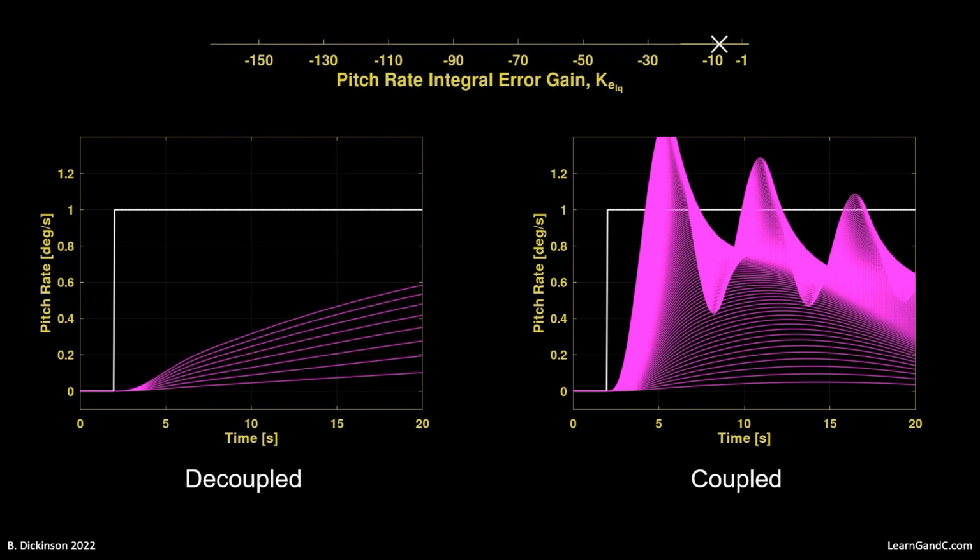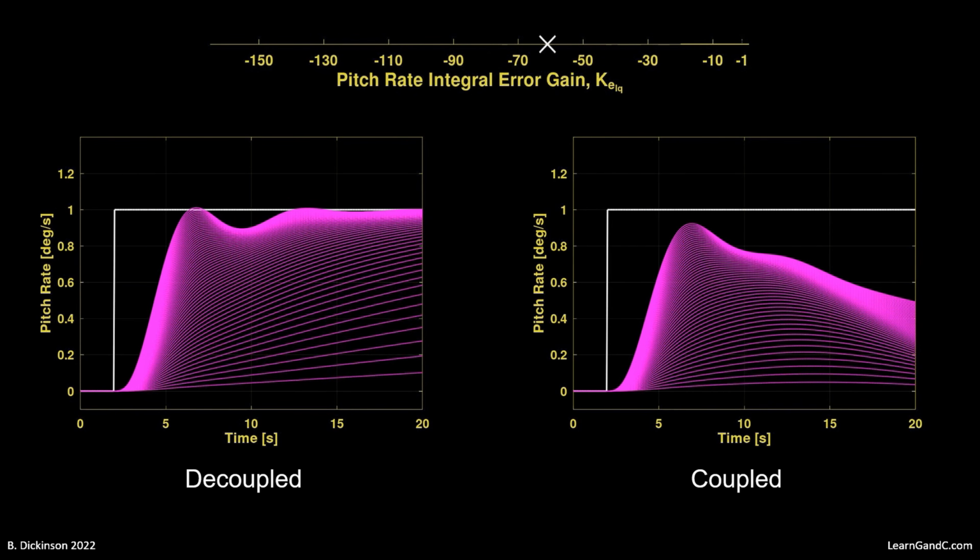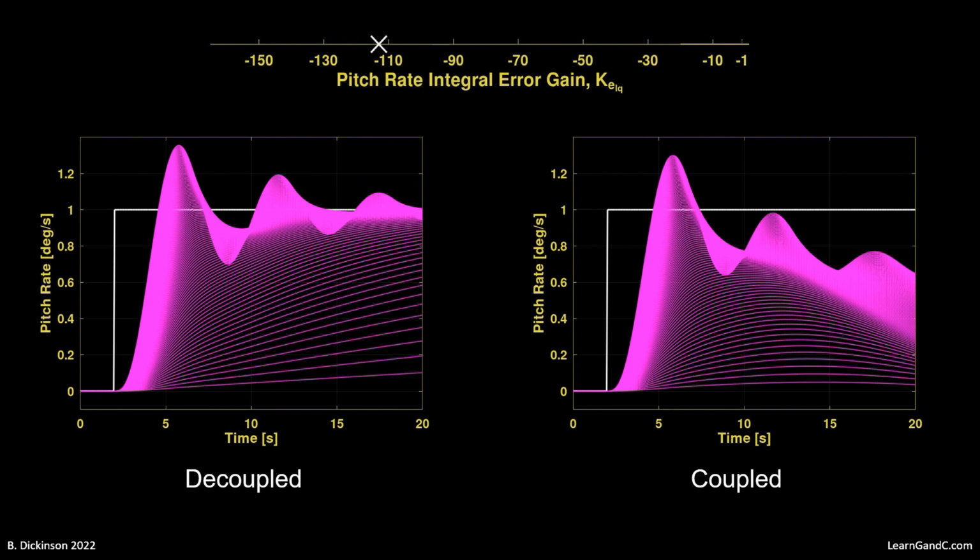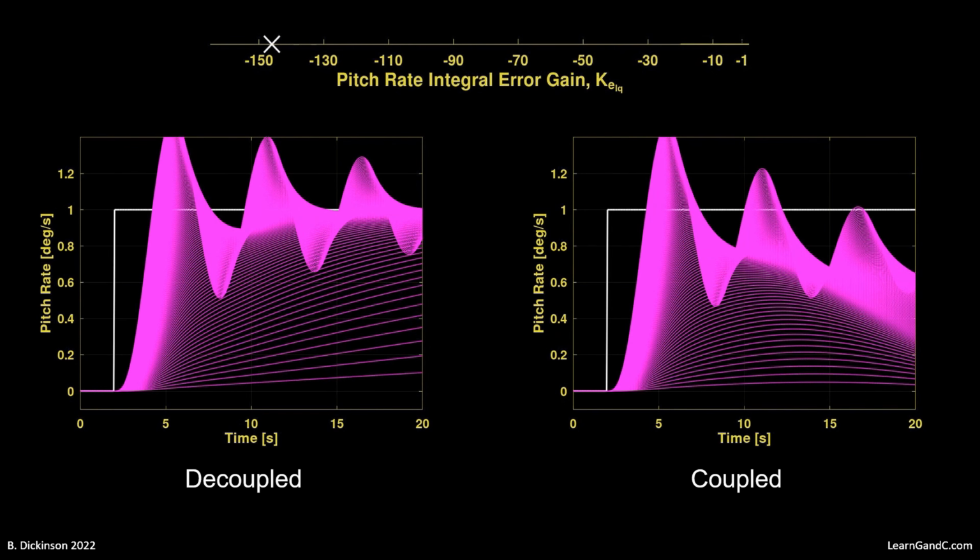In the decoupled system, we find a mean steady-state tracking of the pitch rate. And as a type 1 controller having a single integrator, it's consistent with our expectations. So this exercise shows us modal coupling. But in the end, we can't decouple the modes with this control architecture. But at least we understand the effects, so we're not left wondering when we analyze the controller in a nonlinear simulation.